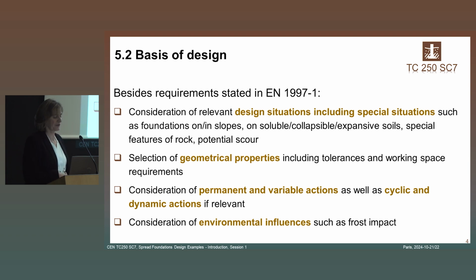There's something said about the selection of geometrical properties, including setting out tolerances and working space, and provisions are given on permanent and variable actions, what type of actions need to be considered or which may be relevant for spread foundations, as well as cyclic and dynamic actions if they are relevant for your design. There's also a consideration of environmental influences. In the case of spread foundations, it is specifically frost impact that needs to be considered.